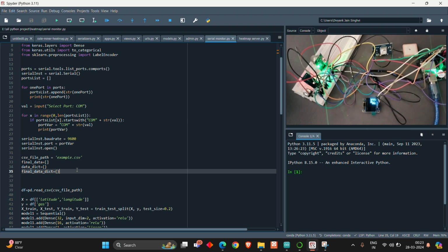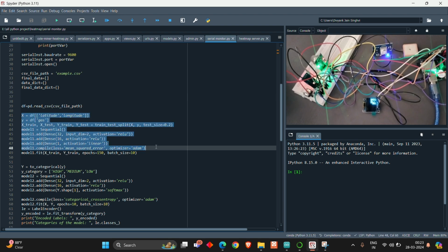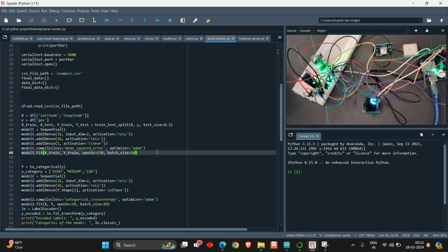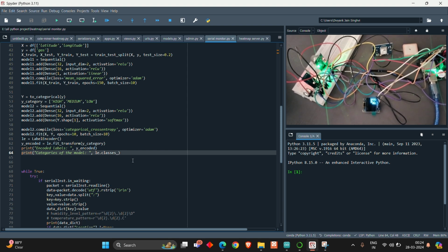If the gas value is above 8,000, then it will be 8191, which is the default value of the gas sensor if it is not able to read. Okay, so this 8191 value helps to detect that there is an error.